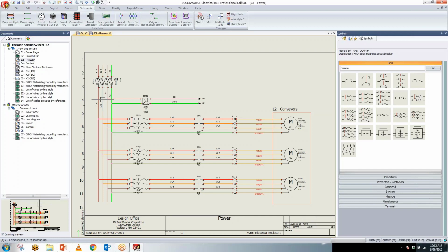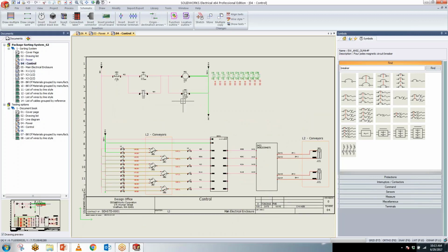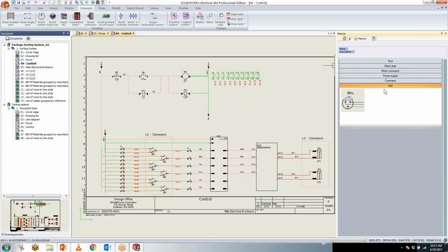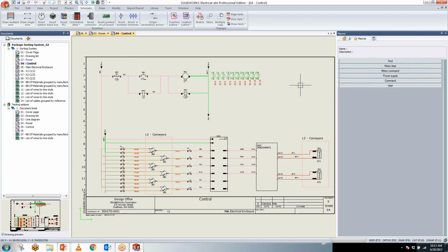And we're going to see that in a minute, but before that, I'm going to show you guys how this particular schematic is connected to another schematic that has all the macros in it. Like for example, those cylinders here are macros that were stored in the macro palette here. You can always generate your own macros by just drag and select components and put them in your palette. That's going to be stored for later uses.